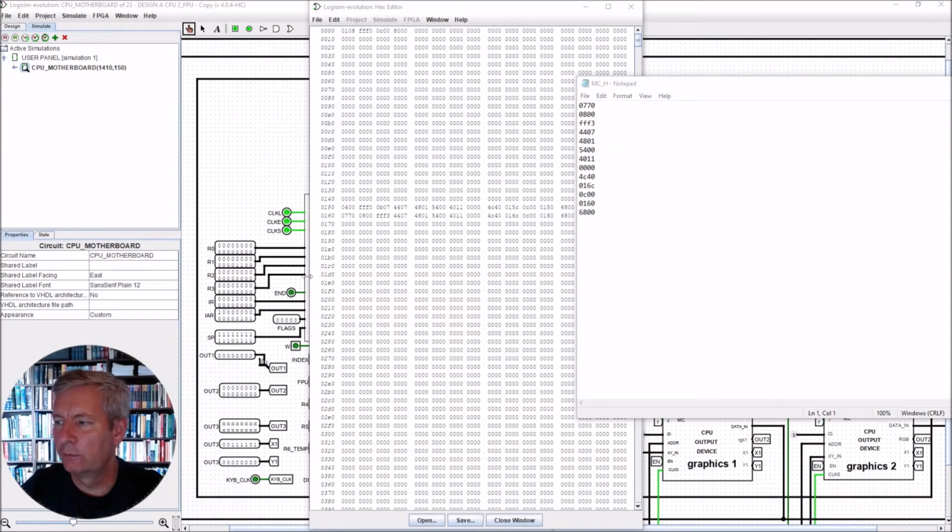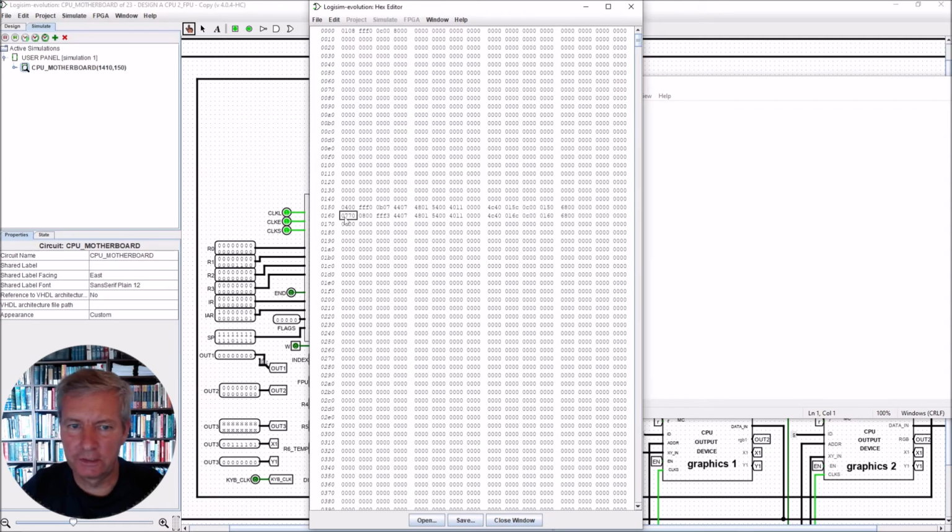So I have assembled that piece of code, and I have the machine code here in hex. So I've taken this machine code in hex and I've entered it into this address position here. So it starts at this position here, and I've entered the values in. So this is going to be our print character subroutine within the ROM.